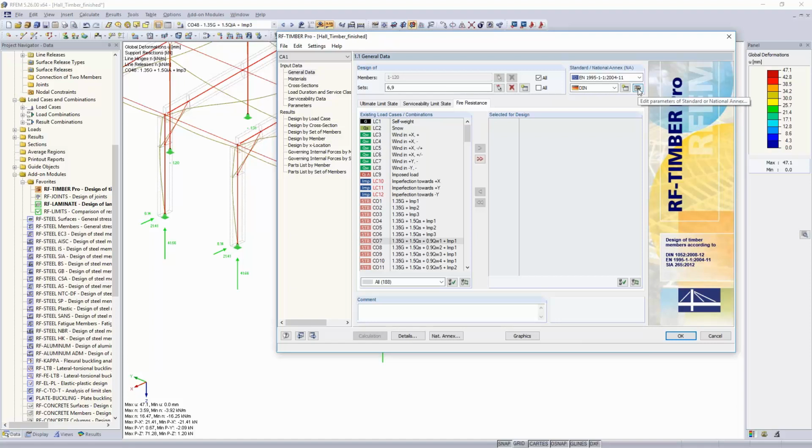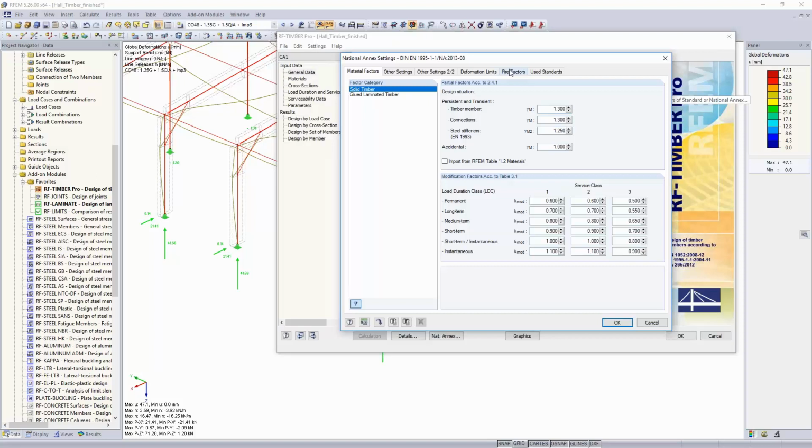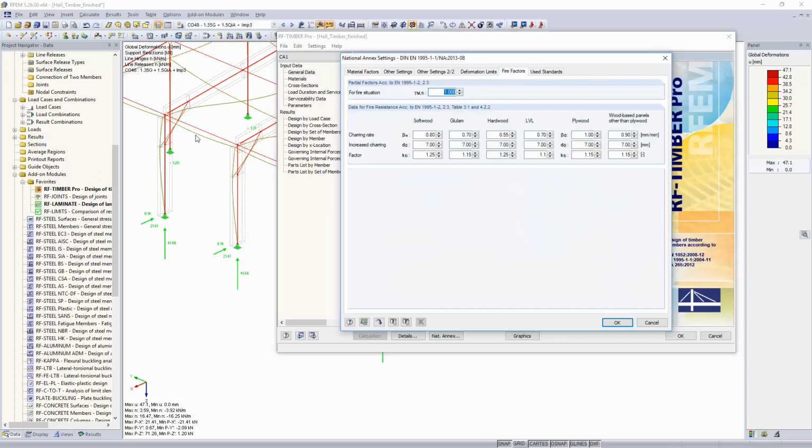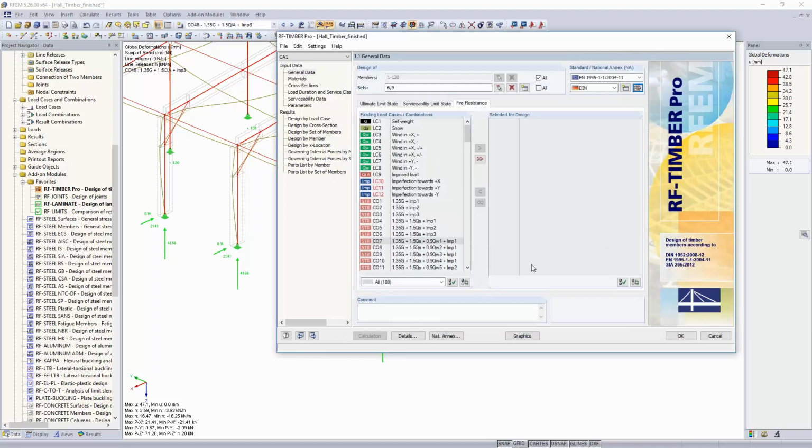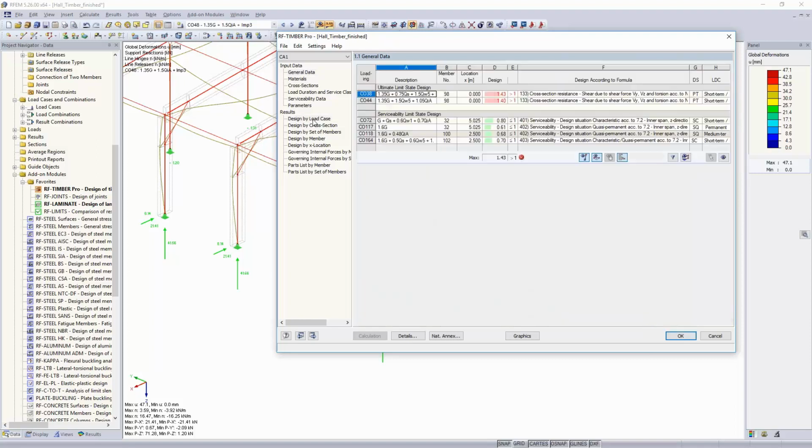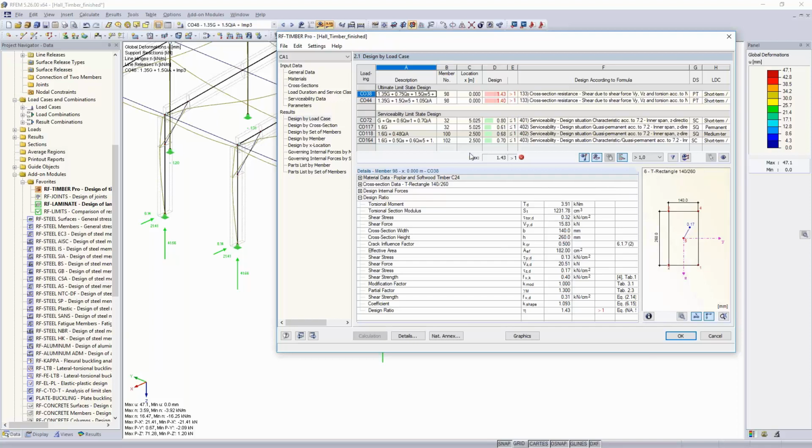And then what we do is that we reduce the section, or all the sections inside here, with the so-called burning rate. And according to this burning rate, we do all the verifications for the ultimate limit state again with the reduced section. So in general, it's also not so fancy to show, as it is actually the same as what we have here in ultimate limit state. Okay, hope that explains it.